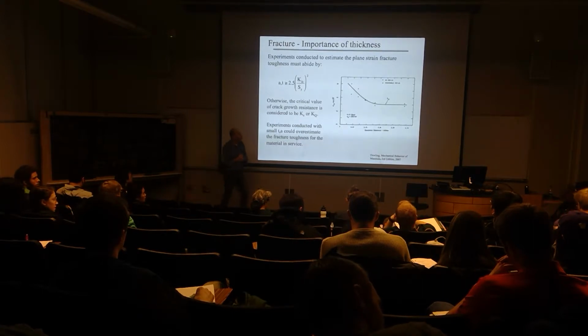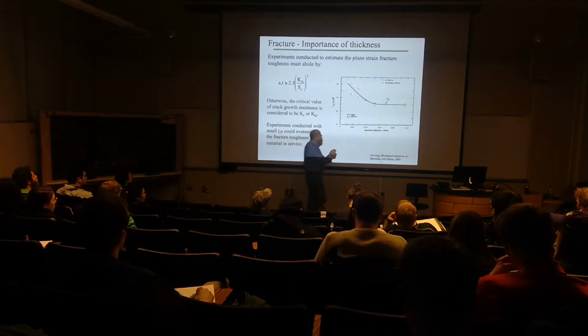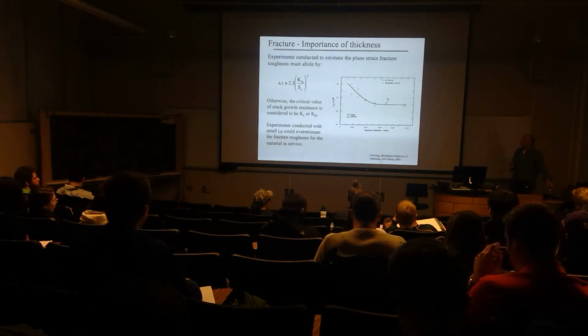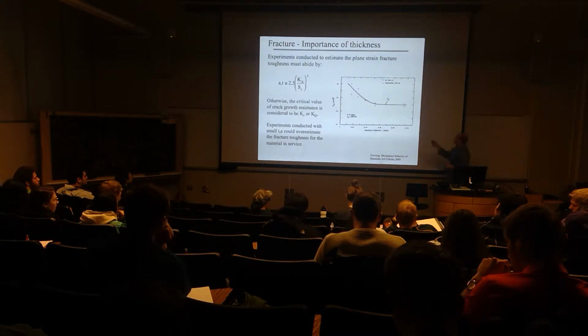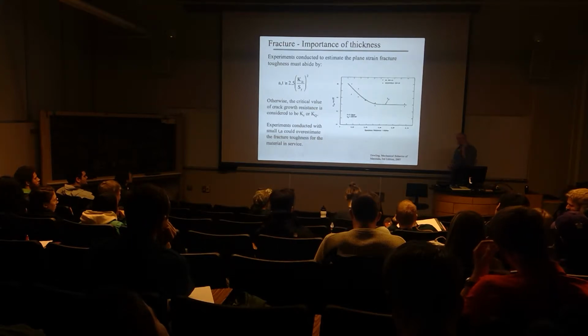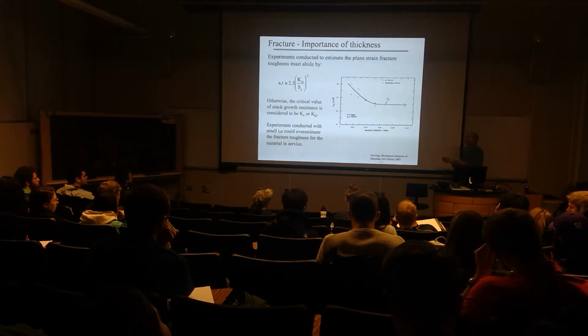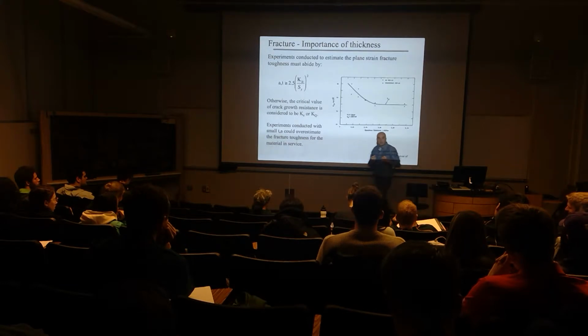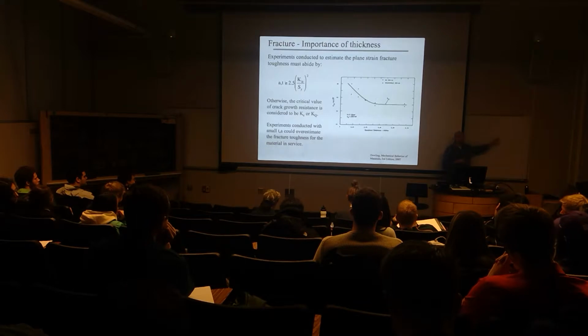Yes. Up in the corner there, pop-in. Pop-in means that the crack popped in. That means that the crack popped in without any additional deformation around the crack tip. So pop-in would mean that it's a dynamic snap-in of it. And so in this case, these black dots represent the fact that the material was brittle enough that when enough opening load was applied, the crack popped in, it initiated dynamically in order to be able to continue.